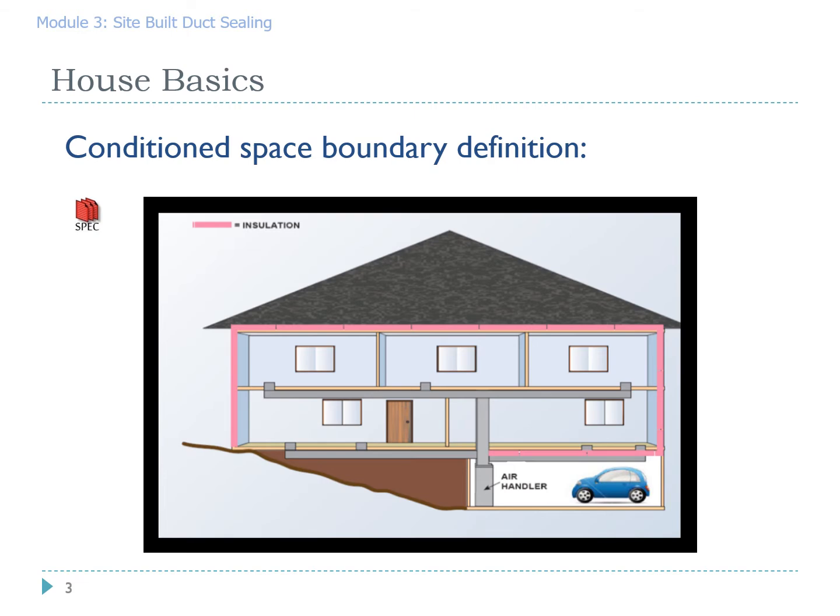In order to be eligible for this program, at least 30% of the ductwork must be outside conditioned space. Sometimes it's obvious, sometimes it's not so obvious. In this two-story house, we can see that we've got ducts between floors. Those are obviously inside the conditioned space. However, we've got ducts in a crawl space, that's outside the conditioned space, and in the garage, and garages are almost always considered outside. In this case, I would easily argue that over 30% of the ductwork is outside the conditioned space and therefore eligible for duct sealing under this program.